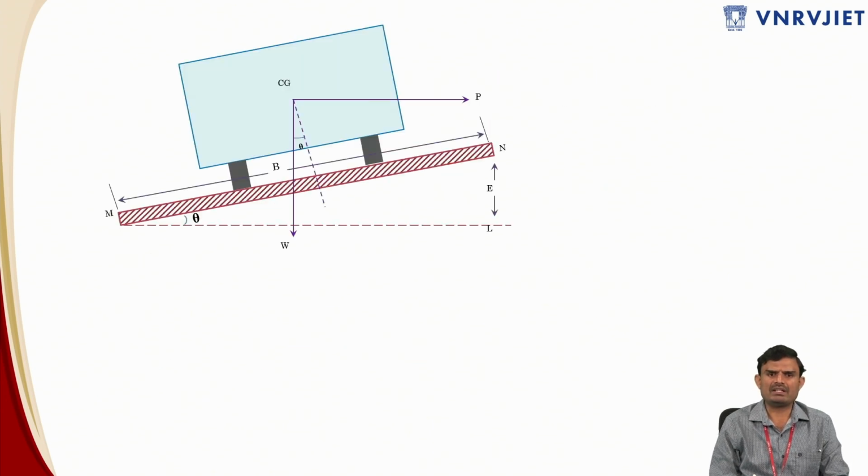And this is the vehicle traveling on a horizontal curve when provided with superelevation. So far we had not seen what superelevation means on a horizontal curve. We have seen only the centrifugal force acting horizontally outwards. Now we are providing some component on the road to reduce the centrifugal force acting on the horizontal curve. That component is said to be the superelevation.